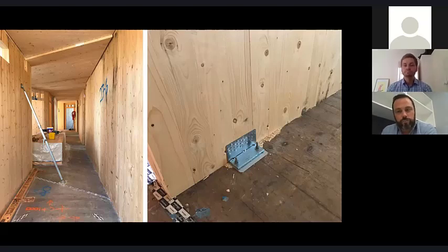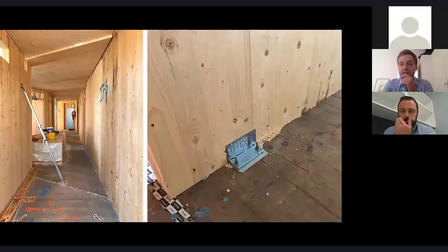So trying to reduce those screw connections and make them more efficient from a design, cost, and installation side is much, much more efficient, because any subby is dealing with one screw all the way up the building for this type of connection. Yeah, you really want to make it as foolproof as possible, and it makes the site inspections much simpler as well, to check that it's been done correctly.